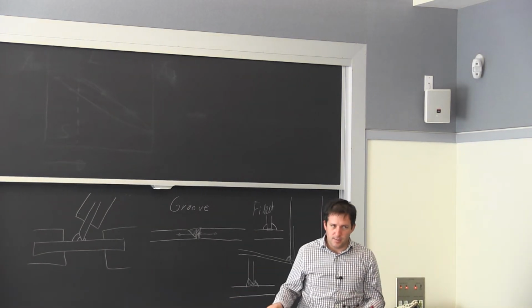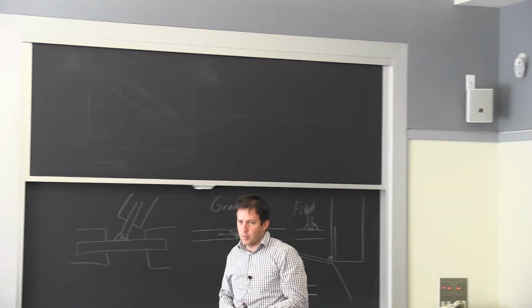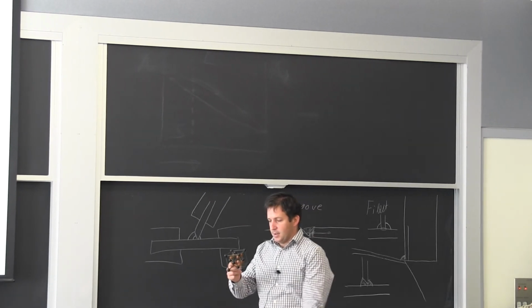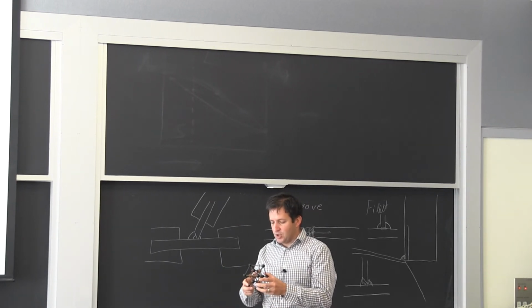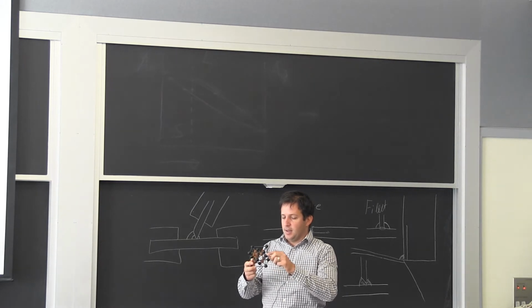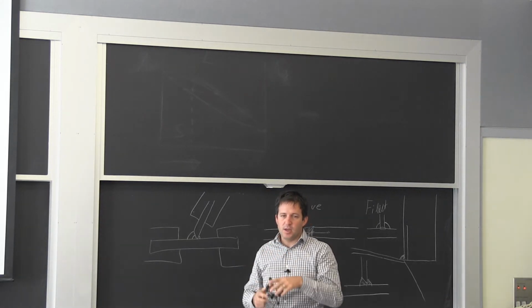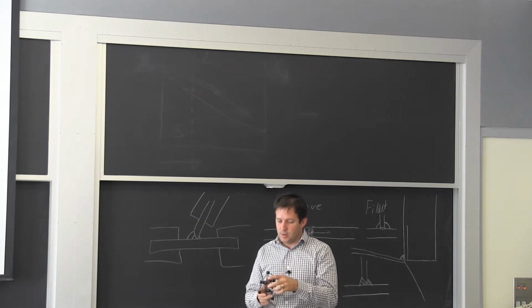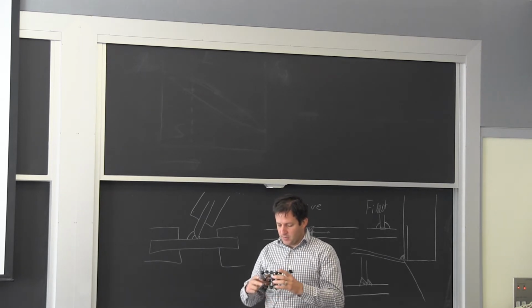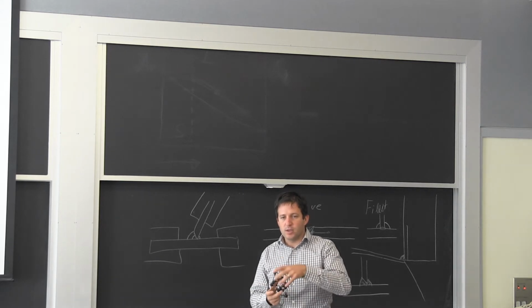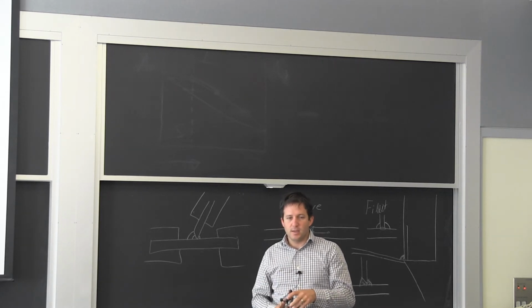I forgot what the cementite is, but it's not deformable. If I'm going really slow and I had this, what happens is I'm just changing it a little bit, and the carbon goes into one plane, one direction, and that's why it becomes tetragonal. Because there's little room here, it's very compact, there's very little room for carbon, and that's why it gets stretched, and you go through that martensite if you're cooling it off.